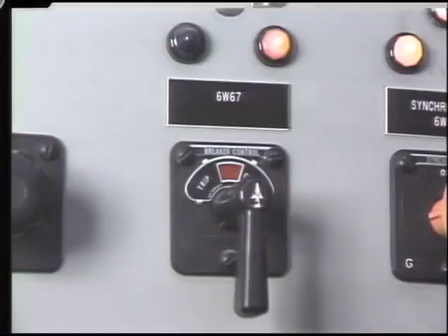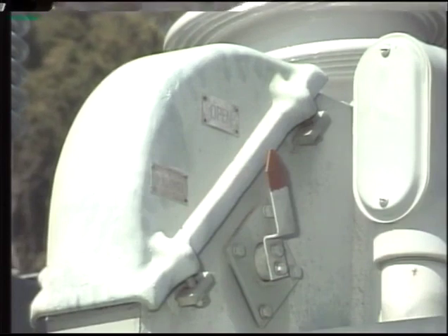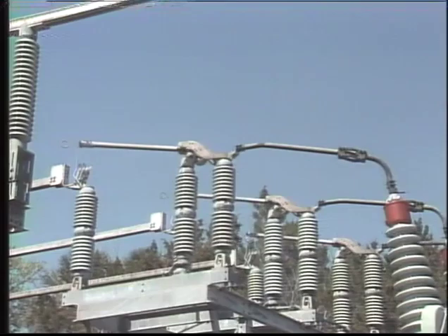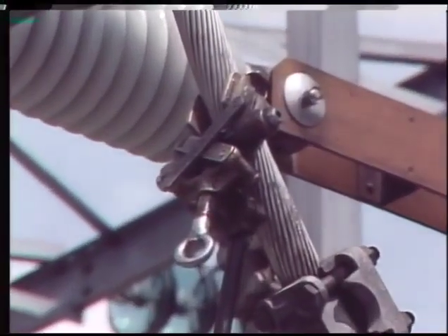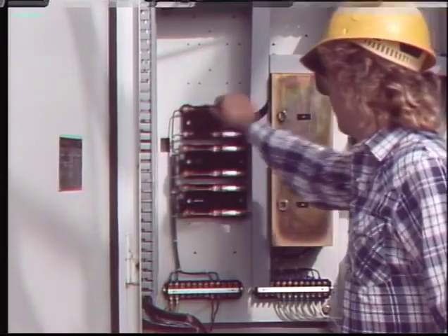In general, a breaker is taken out of service only after the proper clearances have been received. When a breaker is taken out of service, it's first de-energized by opening the breaker. Then it's physically isolated from the system. The breaker is tested for dead and properly grounded. Control circuits at the breaker are also de-energized.